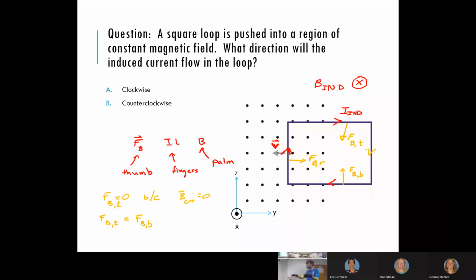Yeah, what happens? You pull the cable, it shortens up. What happens near your front tire? The brake clamps on the wheel. In other words, you shorten the cable, those brake pads press up against the wheel. That's a mechanical part. If you do that long enough, what happens to the brake pads? They wear out and you have to replace them. You take them down to Fitz's, they throw new ones on. They recable your bike if it stretches out, et cetera, and you're off and running.